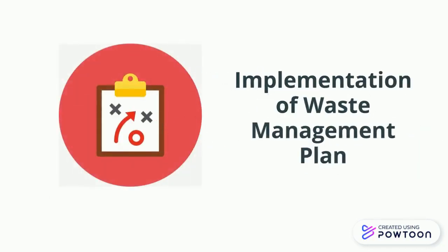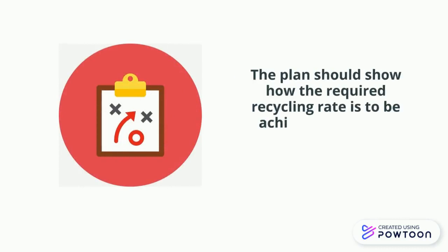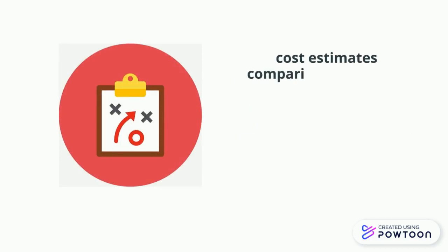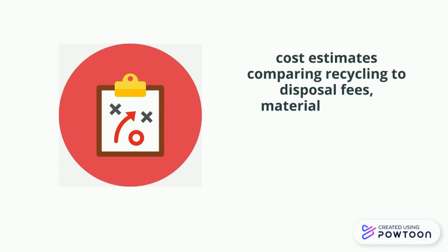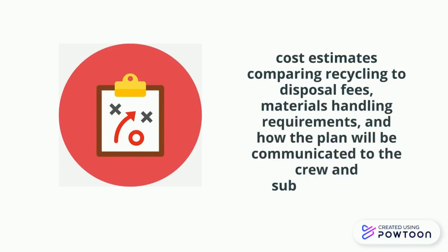Implementation of waste management plan. The plan should show how the required recycling rate is to be achieved, including materials to be recycled or salvaged, cost estimates comparing recycling to disposal fees, materials handling requirements, and how the plan will be communicated to the crew and subcontractors.